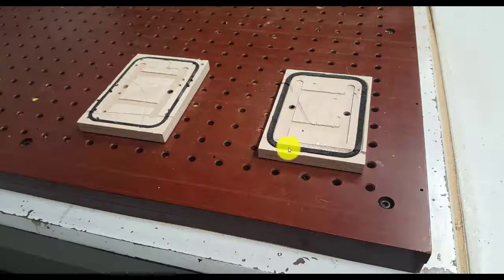This rubber seal will make a very tight seal with the workpiece, so when the workpiece sits on top of it, the suction will come down through the hole there and suck the timber down tightly against that seal. And the good thing about those manufactured on site ones is if there's an accident or if they get damaged, you can simply replace them. And just in practical terms, if there's any little nick or groove in that rubber seal, it compromises the seal and the workpiece may move when the program has actually been processed. And you'll see that in a video in a couple of seconds. You'll see it actually being clicked into place.